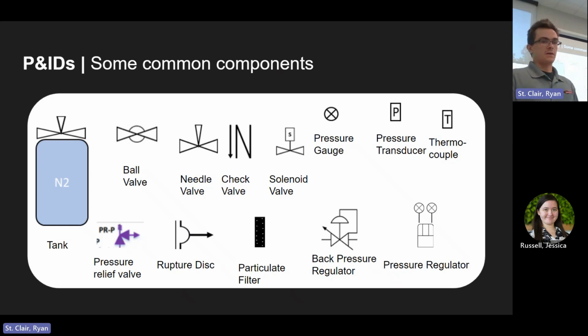It's important to do that because when you have a high pressure oxidizer environment, you do not want to introduce any possible organic contaminants into the system, because they can act as little pieces of fuel distributed inside your oxidizer system. And that's essentially the same as having your fuel and oxidizer be the same line, which you wouldn't want to do because you can get premature ignition in the feed system. So we are sure to filter out any particulates in the system at multiple places.